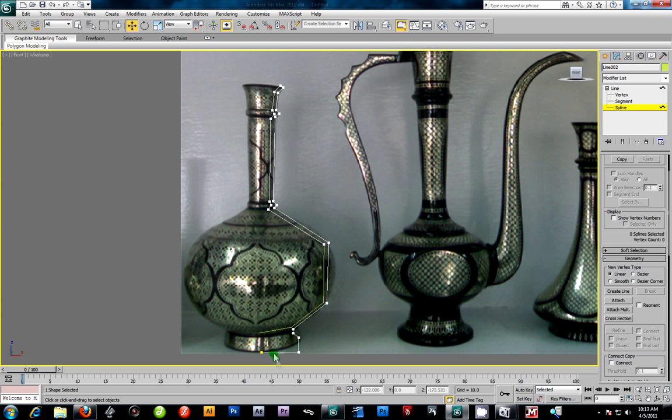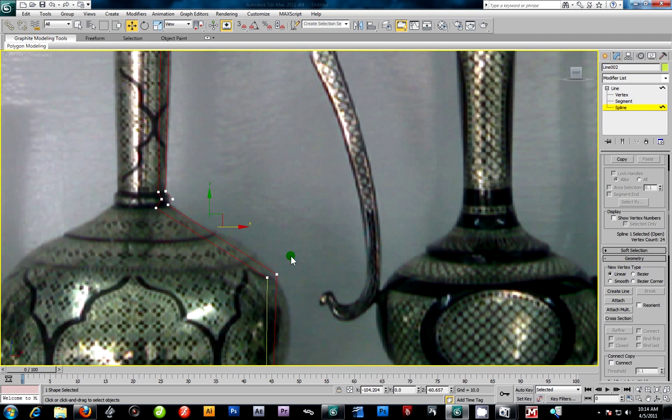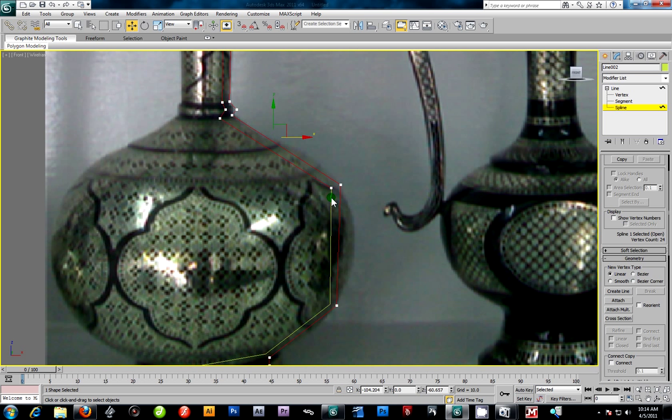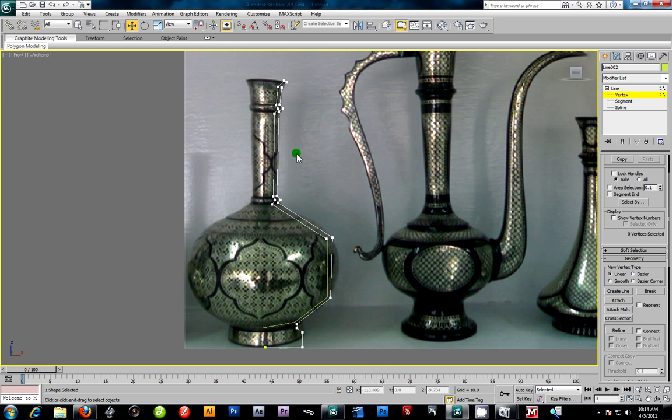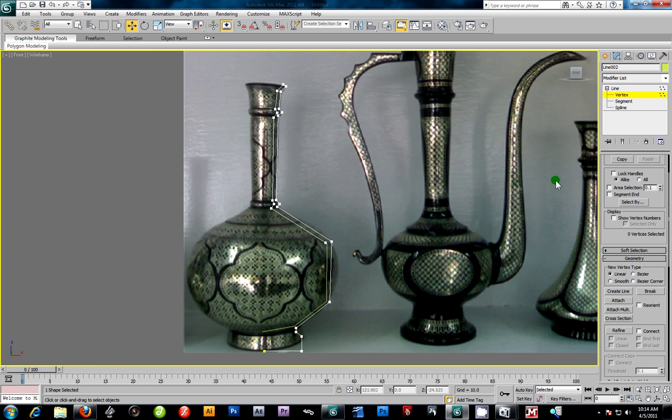In this case, the first line we created, as you can see, we had it connected all the way around and it stopped right there. That's a good way to test if you have openings in your splines that have not been closed off. Always check like that. Click on your spline and check on a line and see if it highlights all the way red. If it doesn't, that means one of the vertex points is not connected. If I grab a vertex point and click on that, I can see that it's not connected. So the next job for us is to shape out the spline, and first of all, we have to connect it. We'll do that in the next few steps.